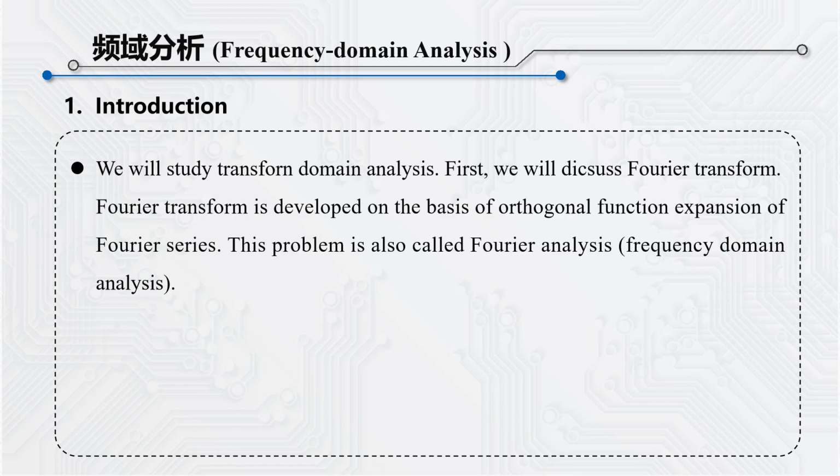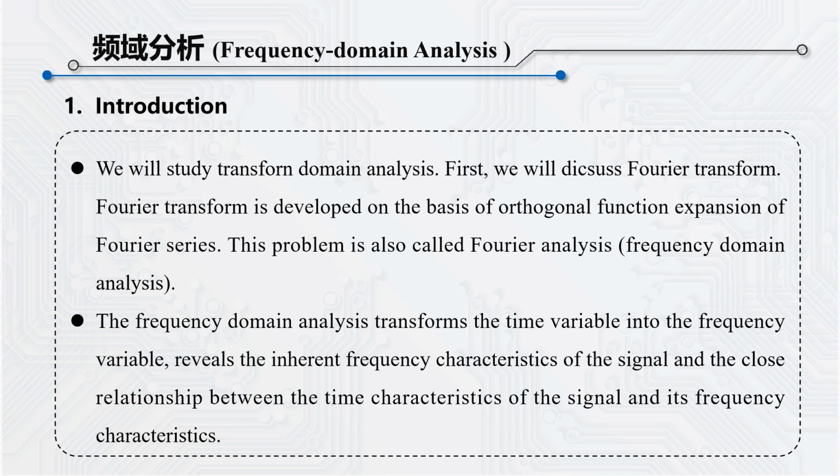In this module, we will study transform domain analysis. First, we will discuss the Fourier transform. Fourier transform is developed on the basis of expansion of orthogonal function of Fourier series. This problem is also known as Fourier analysis or frequency domain analysis. Frequency domain analysis transforms the time variables into the frequency variable and reveals the intrinsic frequency characteristics of signal and a close relationship between the time characteristic and frequency characteristic of signal.